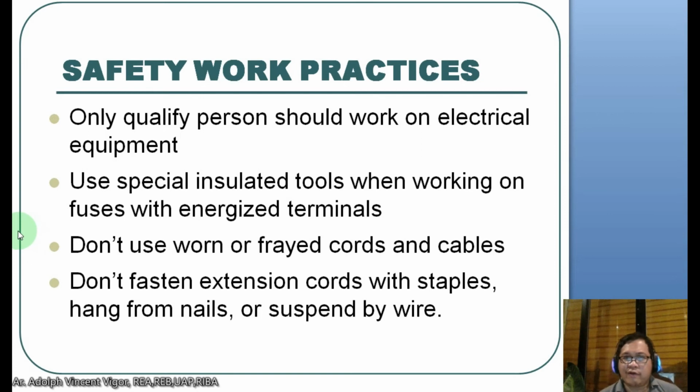Then for safety work practices, only a qualified person should work on electrical equipment. It means your master electrician or even your electrical engineers. Then use special insulated tools when working on fuses with energized terminals. Don't use worn or frayed cords and cables. Don't fasten extension cords with staples, hang them from nails, or suspend them by wire.